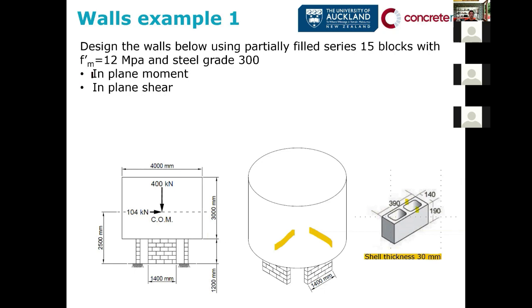And we are going to design the in-plane moment and the in-plane shear. I am ignoring the out-of-plane capacity of that wall if the load is coming in that direction. And I am assuming that only that wall and that wall are taking that load.